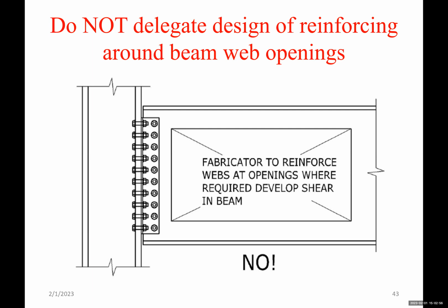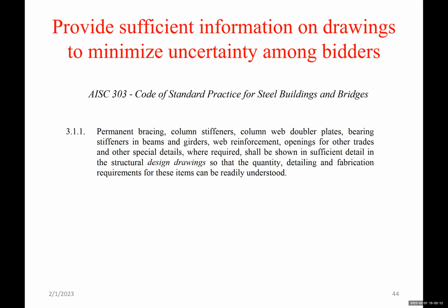There's a design guide for that. There's an AISC design guide for reinforcement around web openings. Now, do not delegate this. You have to do it as a structural engineer. Do not delegate this design to the fabricator, okay? And there are other types also that you have to do yourself, even if you are delegating the connection design.